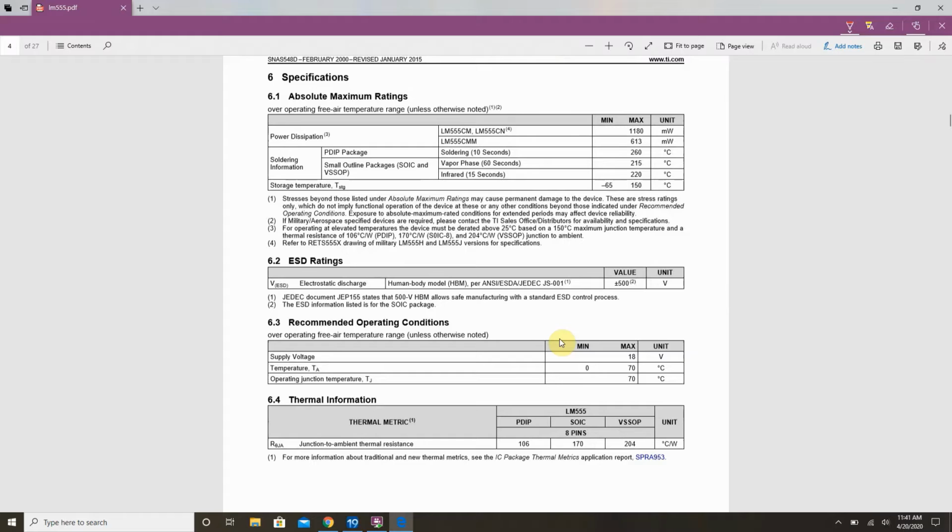All right, and the transistors and the diodes, we always went over the absolute maximums. Okay, when we talk about absolute maximums, that's exactly what we mean, absolute maximums. That doesn't mean that's where you want to operate this chip. For example, if we go to supply voltage down here, it says the absolute is 18 volts. Well, that's great, but we can't operate it continually at 18 volts. You'll destroy the chip, and I'll show you why in a little bit. But these are the absolutes. We do not want to operate at 18 volts, okay, for fear of damage.